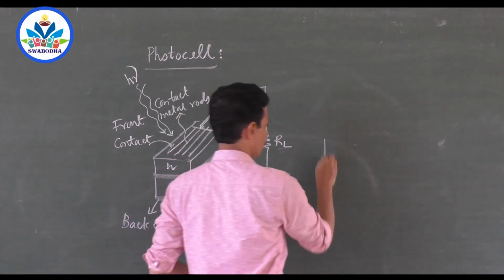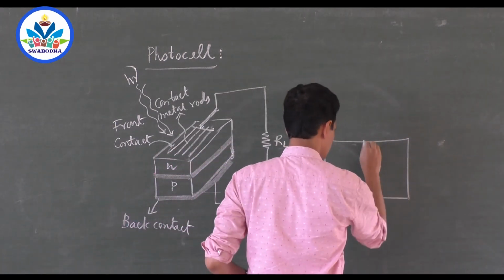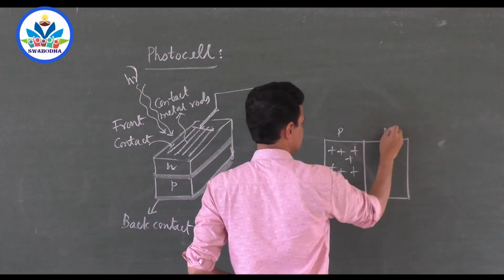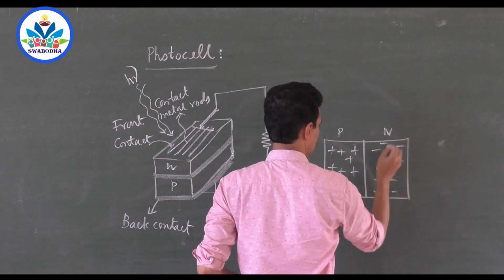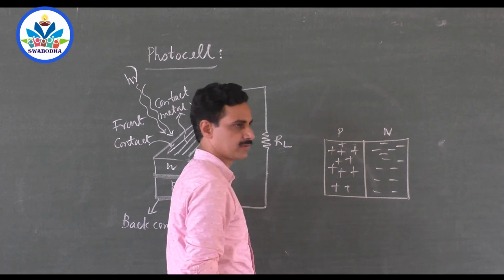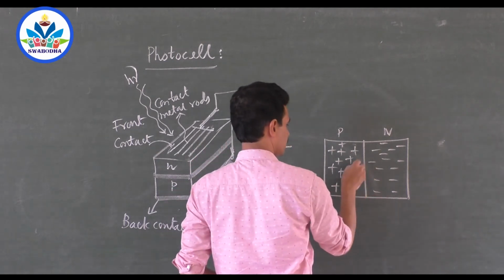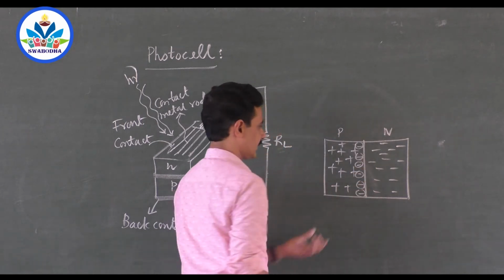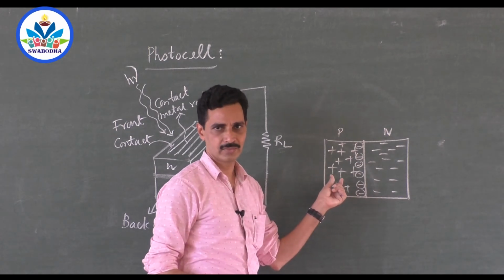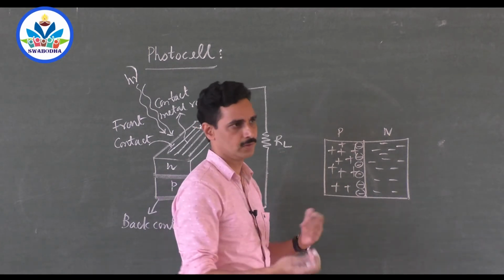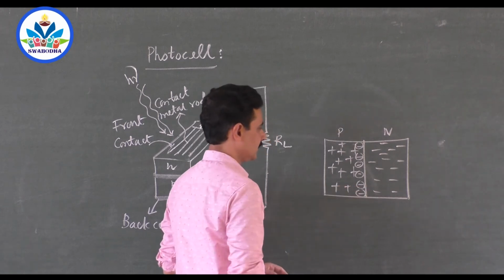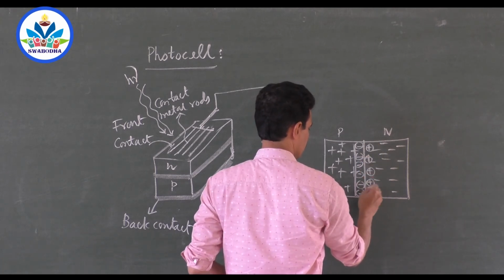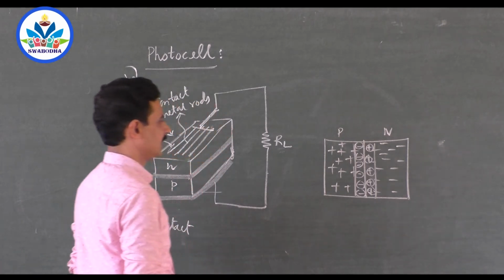And in a PN junction, you know, once the PN junction is formed, suppose this is the P side with a large number of holes, and this is the N side with a large number of electrons, you know that these electrons and holes will cross the junction. In the beginning there is a diffusion. Electrons will move here and become immobile ions by joining with the trivalent impurity. There is a trivalent impurity here which has 3 valence electrons. It cannot satisfy the bond with all the neighboring silicon atoms, so it needs 1 electron. So this electron comes and joins. So there is a depletion layer. These atoms have lost 1 electron. So like this, the p-n junction is formed.